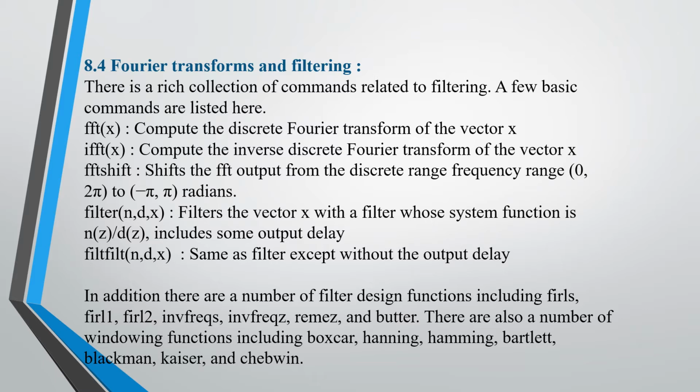In addition, there are a number of filter design functions including fir1, fir2, firls, invfreqz, remez and butter. There are a number of windowing functions including boxcar, hanning, hamming, bartlett, blackman, kaiser and chebwin.